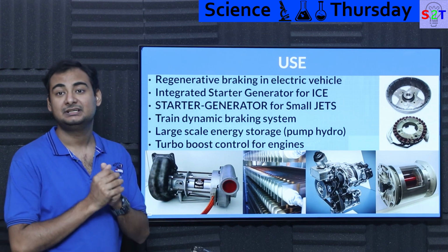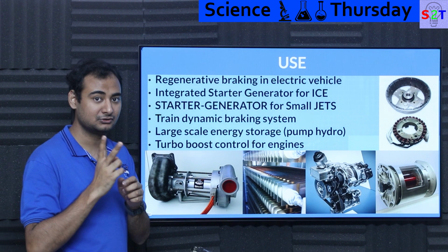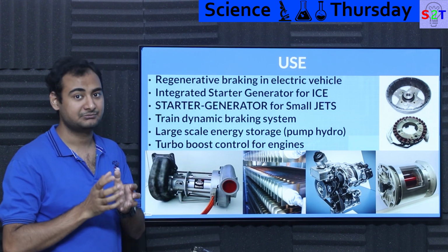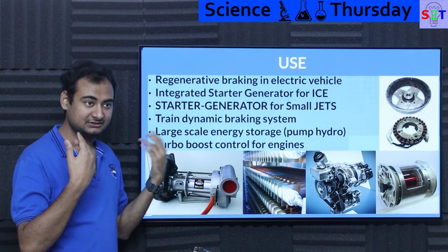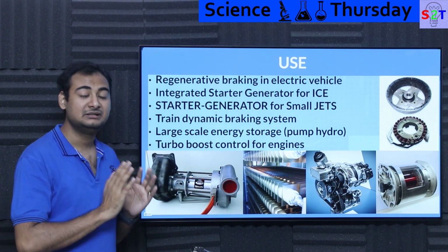The benefit of this is you are basically collecting thermal energy, because that exhaust has two components, gas volume and temperature. Both of them are helping you to spin the turbine. So that's why it's called the thermal energy recovery system. So turbo boost is done. Now this is not limited to F1.